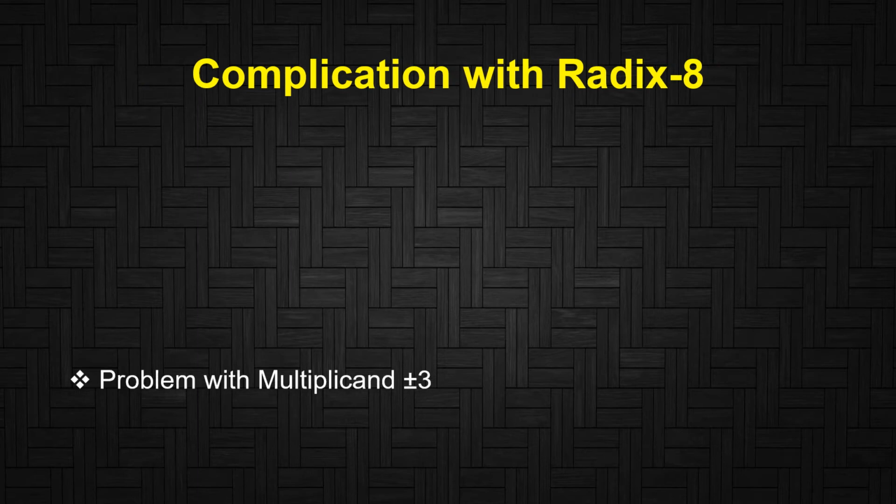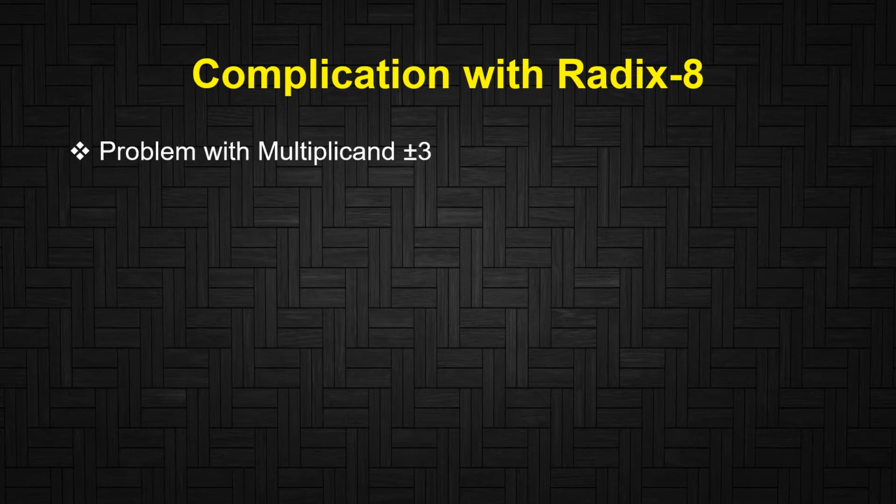The design of the approximate radix 8 booth multiplier generates a small number of partial products and thus requires fewer adders to accumulate partial products as compared to that of radix 4. This is because generation of plus minus 3x multiplicand in a radix 8 encoder requires a preliminary processing. Therefore, a higher delay of 10 to 20% is observed compared to the radix 4 algorithm.